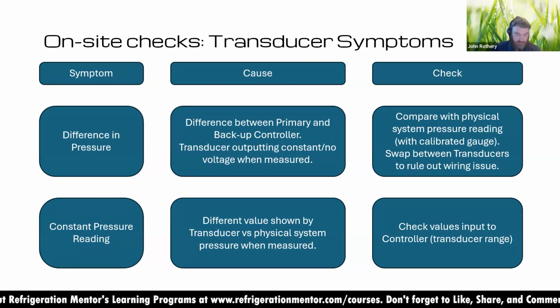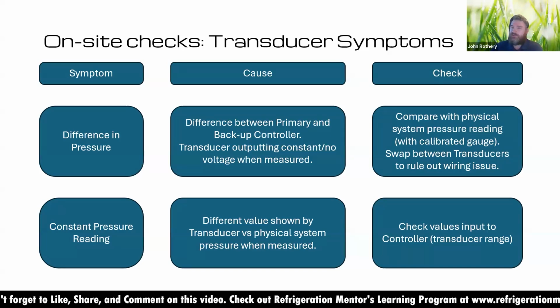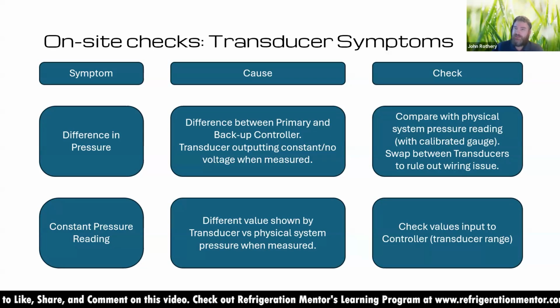Yeah, I've seen that before, especially oil logging. When they've been installed and it sort of forms a trap and the oil migrates and hits the transducer, it causes it to read incorrectly. I've seen that before. Obviously, one check you can do if you've got a backup controller is compare the two, just as a comparison. I think we got that on a slide as well somewhere. So yeah, it does happen. I have seen it.